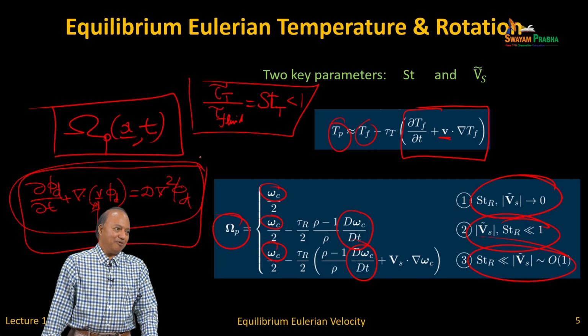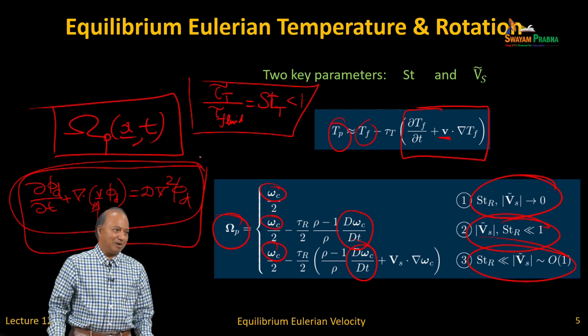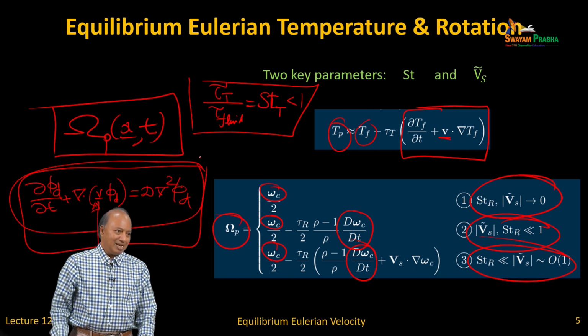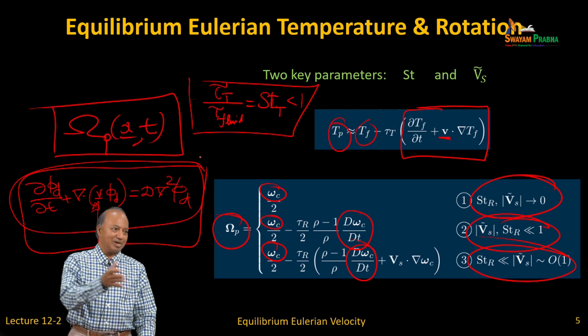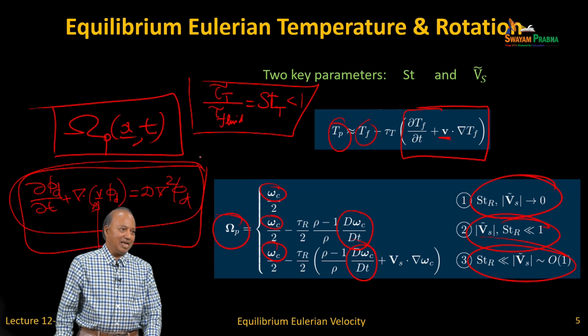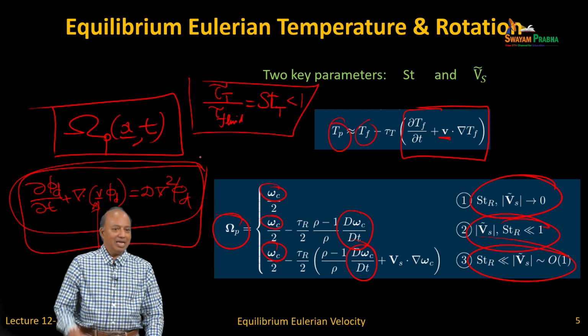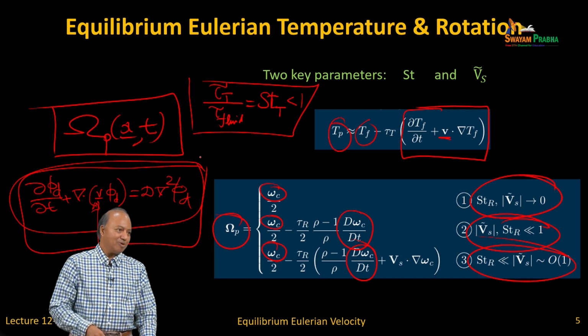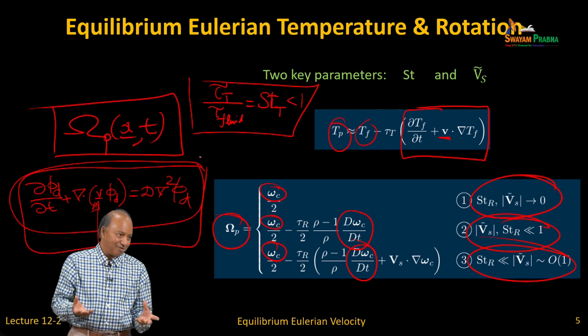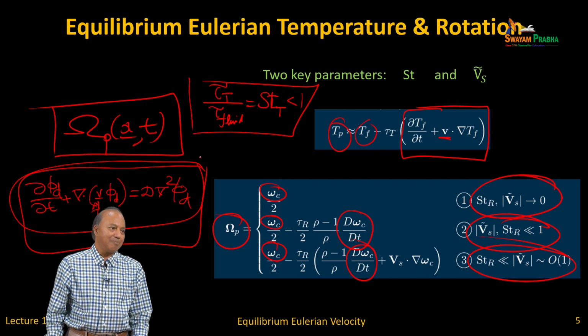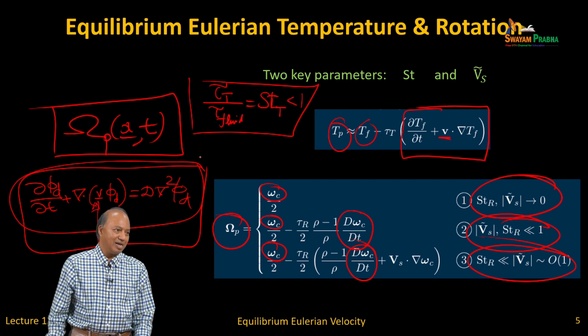Okay, it's a turbulent flow, right? Yes, sir. Then you should do averages, because instantaneously, if you measure in your experiment, it's a random process and your simulation won't exactly match it. So I would say you should do a time average of your data, yes. And in the Euler simulation you average over some volume. So you should also do some time average and try to compare with your measurement.